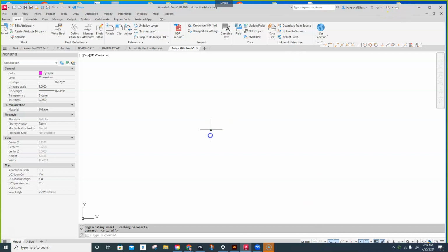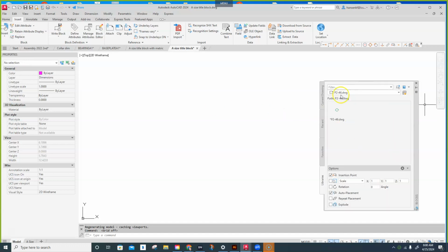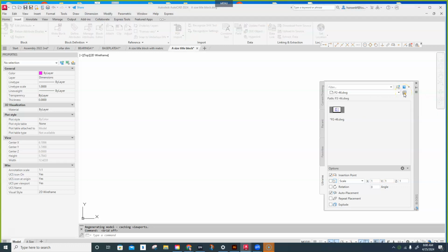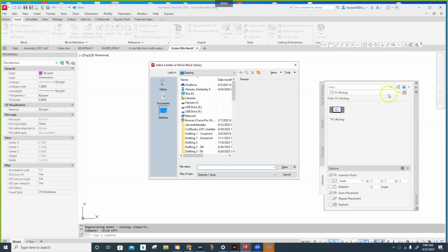All right, so everybody agrees we created a new drawing called bearing. I'm now going to insert that bearing into my current drawing. So I'm going to use the insert ribbon, and then I'm going to use the insert command. It's the very first command on the left. I'm going to hit blocks from library, and it's going to prompt my little box right here, and I'm going to have to search my directory and find that file that I saved.